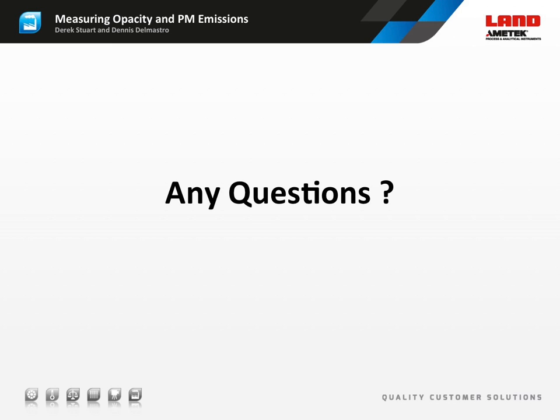What is the highest stack moisture content where I can use an opacity monitor or in situ PM-CEMS? There's no limit to the moisture content, provided the water remains in the vapor phase. However, opacity and PM monitors cannot distinguish water drops from dust particles, so any amount of condensed water will cause problems.